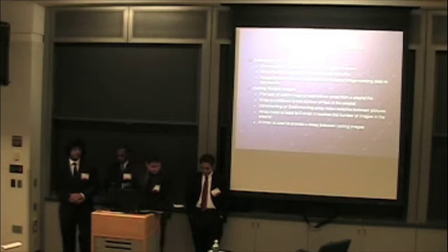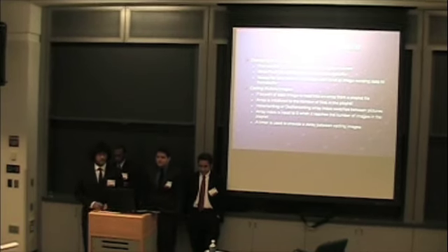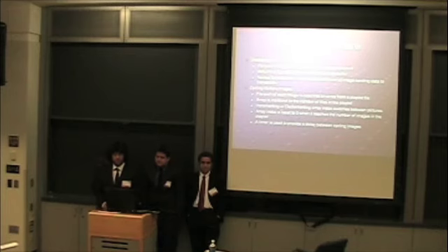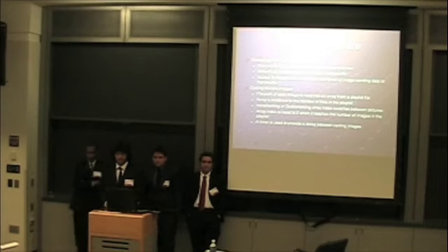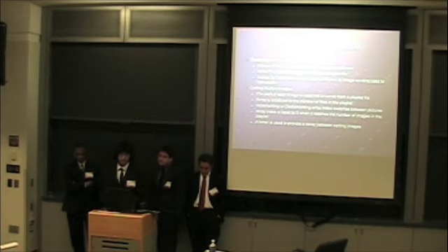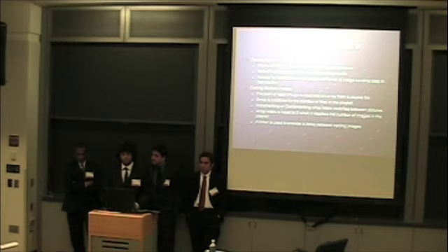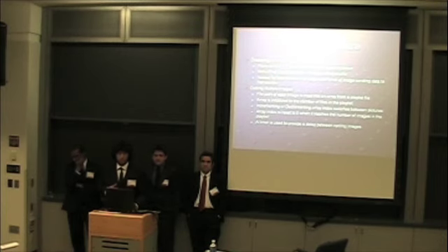The purpose of the slideshow software is to handle and display the bitmap images stored on the device. The software was written in the C programming language and compiled using the ARM GNU cross compiler. The way it accomplishes displaying an image is by writing pixel data to the frame buffer, which is a representation of the image on the screen in memory.